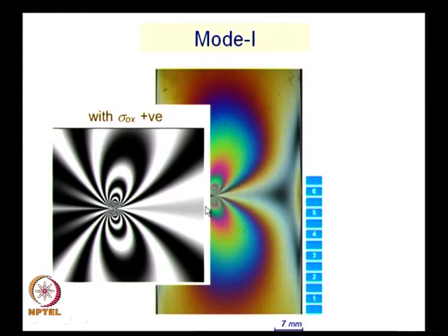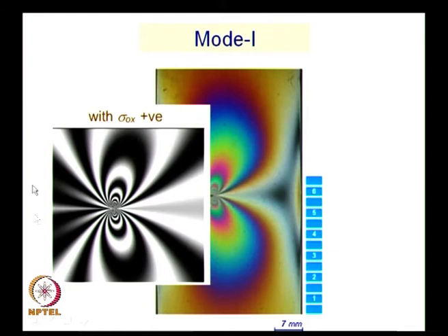If you recall, we in fact got the frontal loop situation for the case of a crack in a pressurized cylinder. The crack was long enough, it was close to one of the boundaries of it, and I also mentioned it is in a stress concentration field. So, in that case you got a frontal loop. People also have noticed when the crack length is longer in the case of SEN specimens, you have a frontal